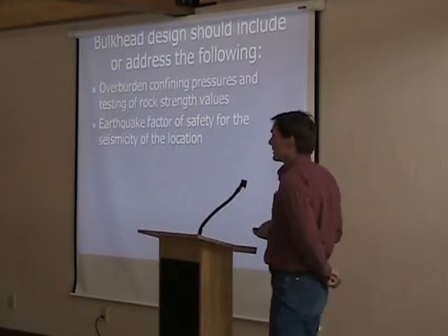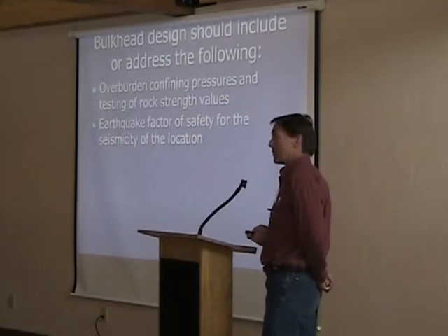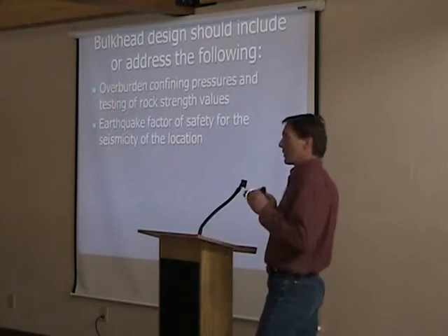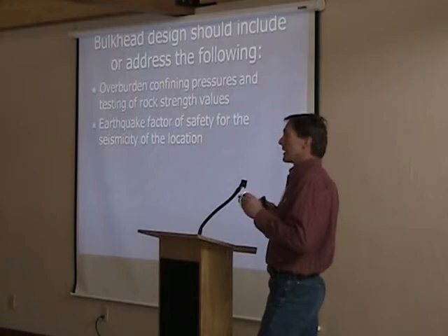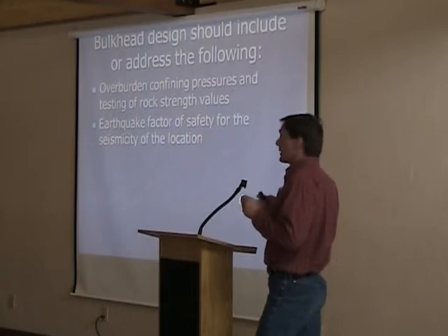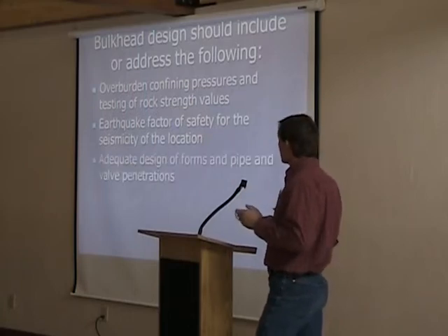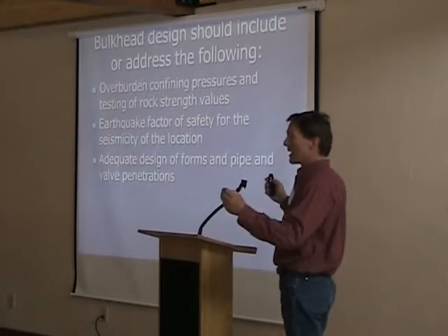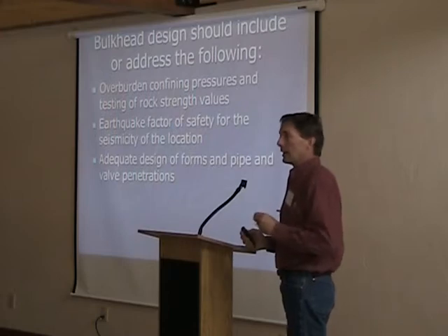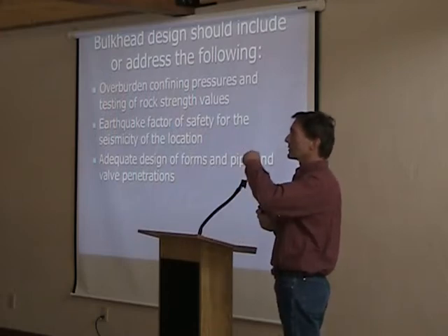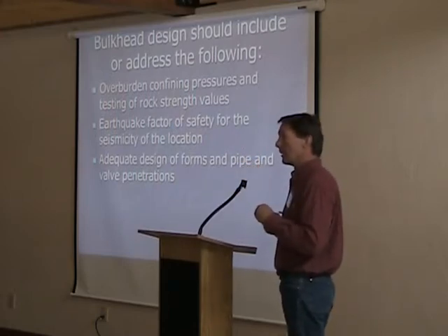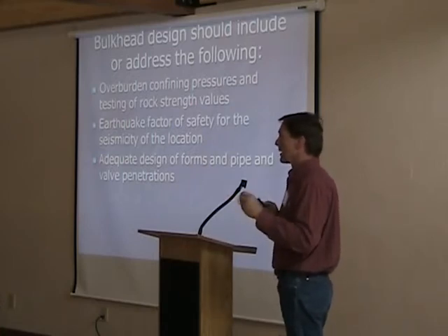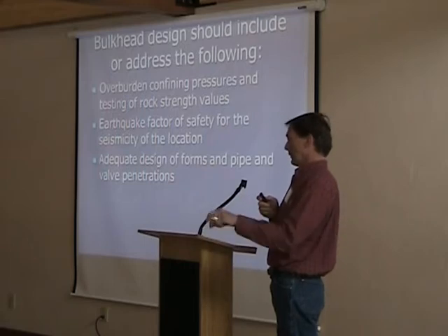We need to make sure that, like building a dam, when you put a bulkhead in, it's an engineered pressure type of a situation where you want to take into effect seismic shaking and earthquake. You want to put in your overburden confining pressures, and make sure that your forms are adequately designed, that you've got a good pipe penetration to measure the pressure, because we need to monitor this whole thing while it's reaching equilibrium, because you still have one last ability. If it's not going to work the way you think, you can open up the tap and drain it off.